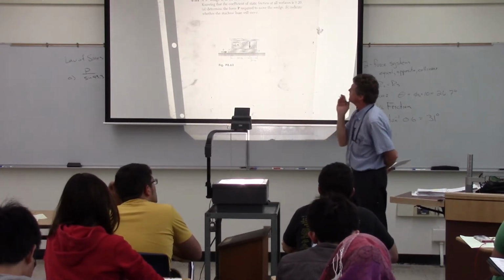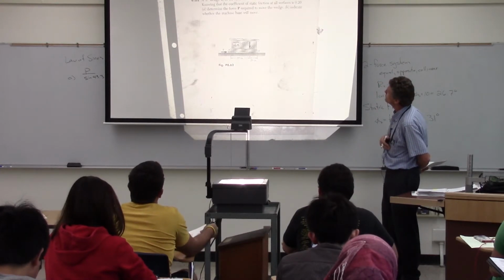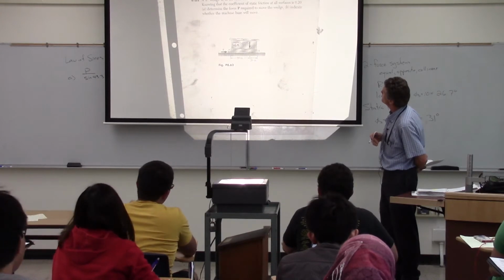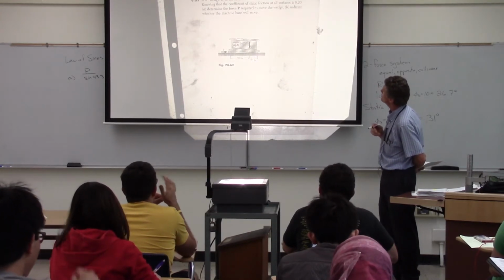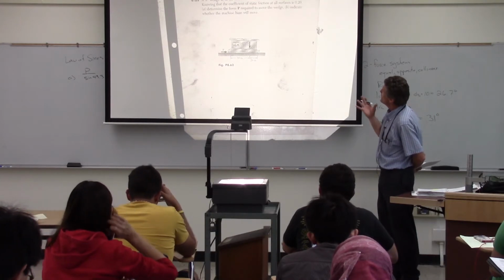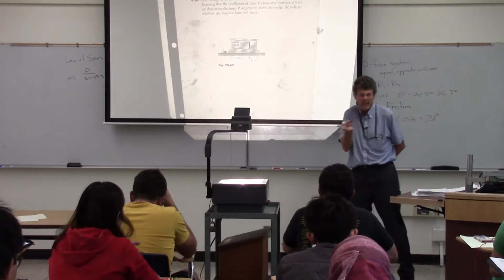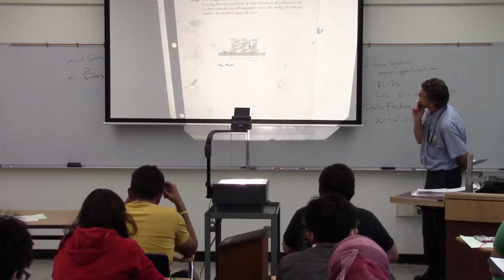Okay, so again, here's a real application. Basically, you've taken a heavy machine piece there or something. You're forcing a 5-degree wedge under it. Coefficient of friction on all of the surfaces is 0.2, so it's a little bit easier. And again, it's going to be that two-step process. What is the force required to get that wedge moving, basically, to get it to start lifting that?